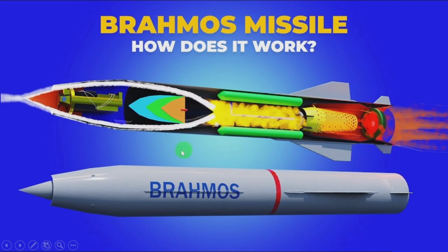going to take. The BrahMos missile consists of its tip followed by the warhead, where the explosive is contained, and later the control of that missile. The later part consists of the fuel and the oxygen tanks, and they supply the fuel and oxygen for combustion in the combustion zone. In the combustion zone, the fuel combustion takes place with the oxygen, thereby releasing high pressure burnt flue gases. And there is a flame arrestor to avoid the burnt flames coming out.